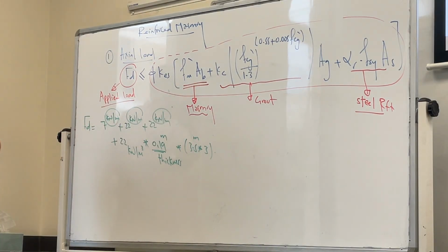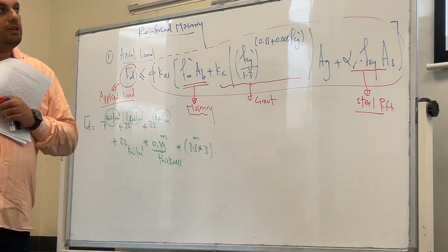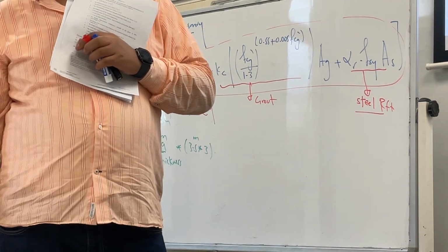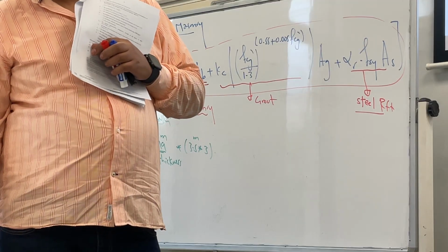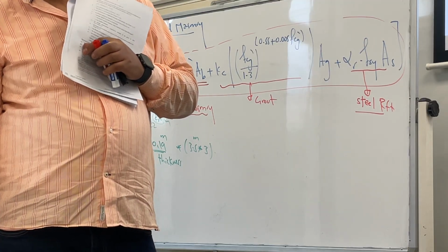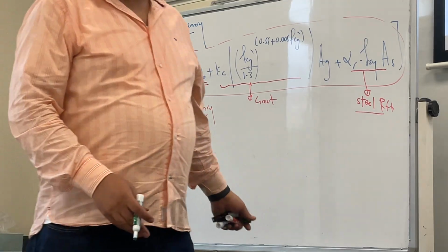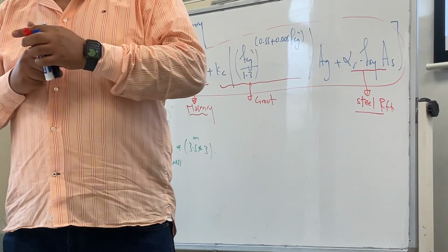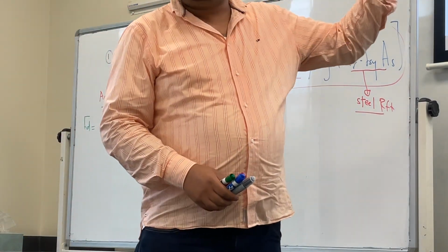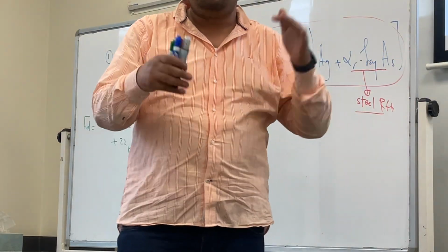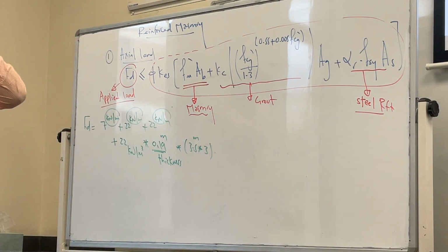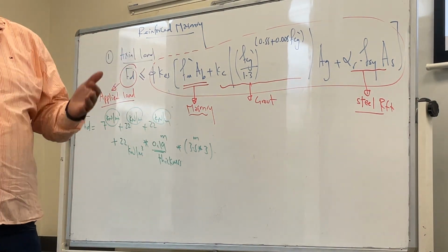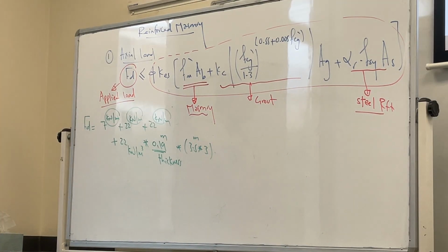But we need to remove the holes. We have the grout, which has a different density. If you want to be more accurate, add the grout. But this is 22, you see, it is as one; we don't remove the holes and then add the grout because it is too complicated. What is 22 kilonewton per cubic meter? It includes the holes, so the density is given for the whole block and mortar together. If you want to be more accurate, you need to add the grout.